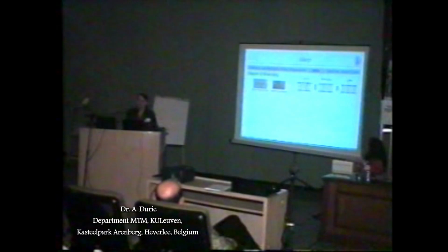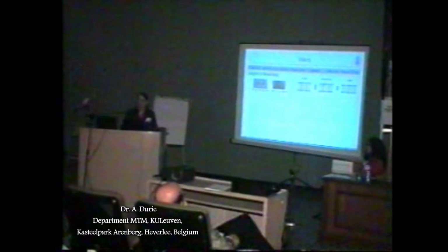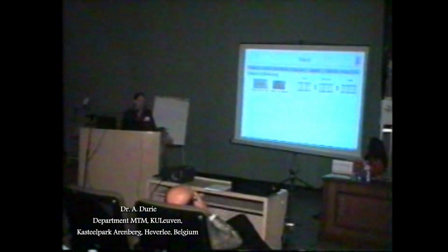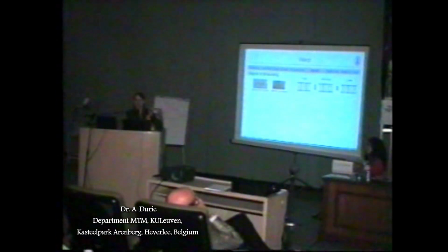If the degree of stretch is quite low, we get a resin area that joins one pile to the next. So our core properties, or the shear properties in the core, which means the bending properties of the core, are a lot better if the degree of stretching is low.